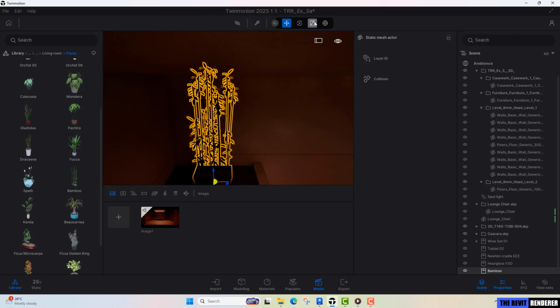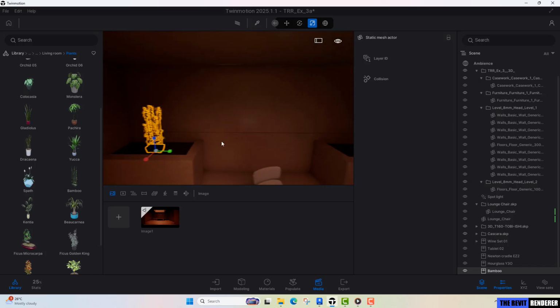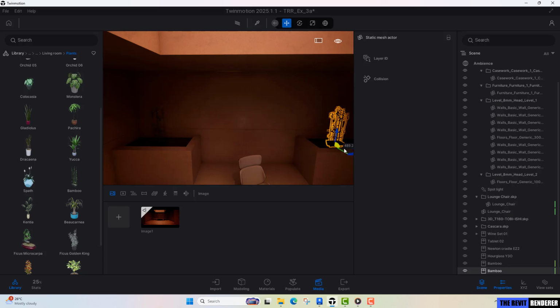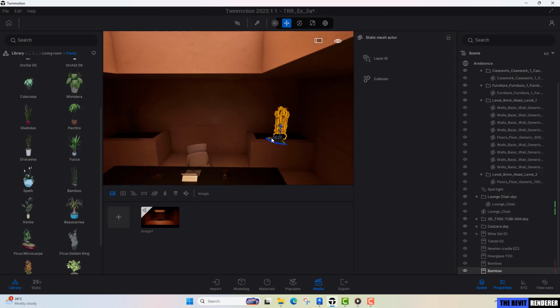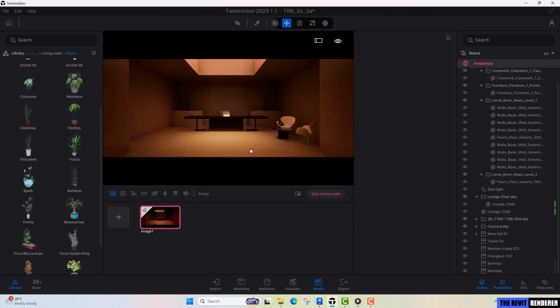It's a bit too big, so I'm gonna scale it again to 0.5, and I'm just gonna copy it to the other side, holding my shift key so that I can copy it as an instance. Okay, I'm gonna place it somewhere in the center. Okay, so the scene is almost complete. Next we'll try to add the projector lights.